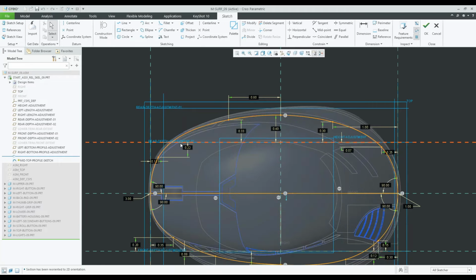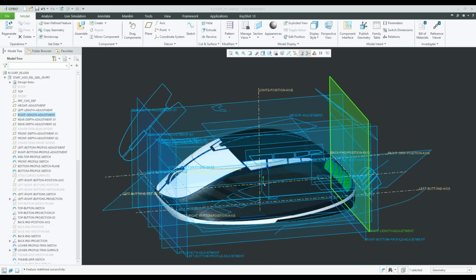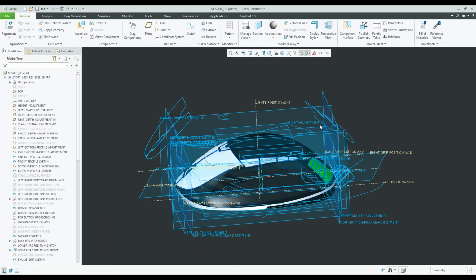So the idea here is that once you establish all this and you have your sketches linked to your different planes that you've created, right? From there, you can just make adjustments to your model by selecting the plane, going into edit, and changing those dimensions, okay? But before I go on and do that, I'm also going to show you how, once I created these initial sketches within Creo, I also went into the style feature or the ISDX feature.